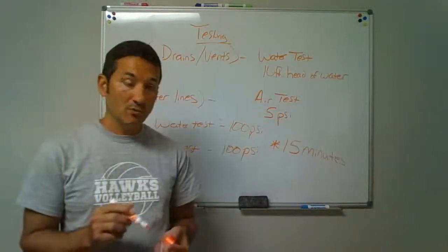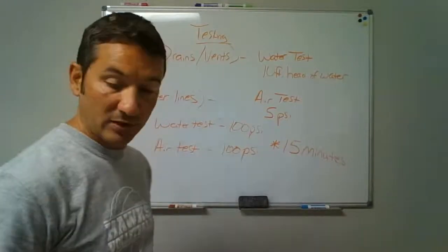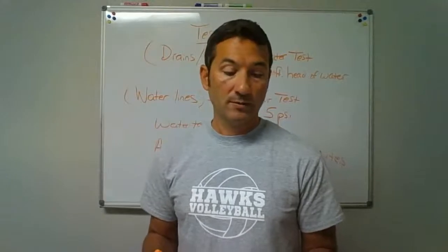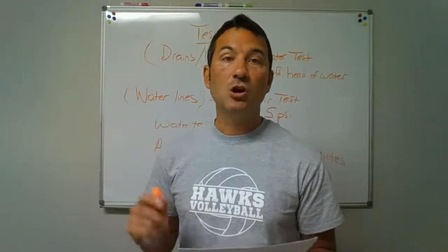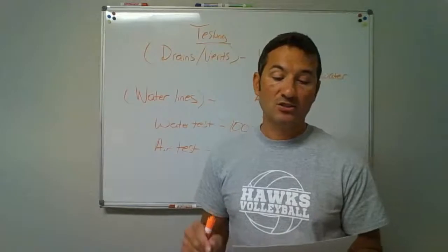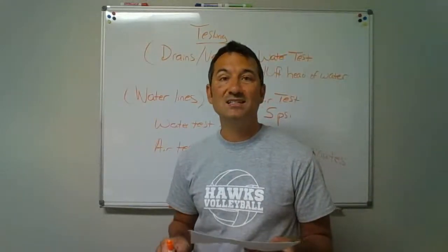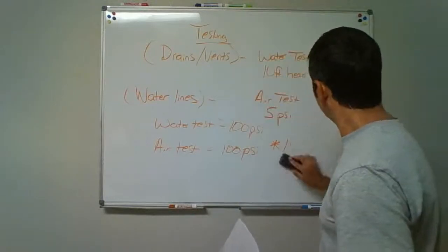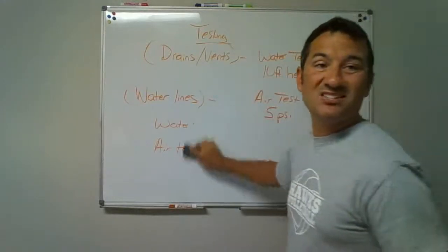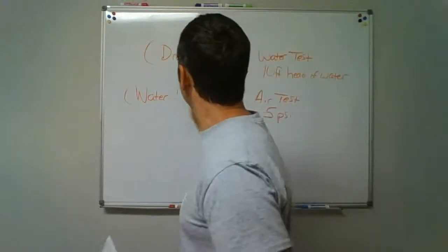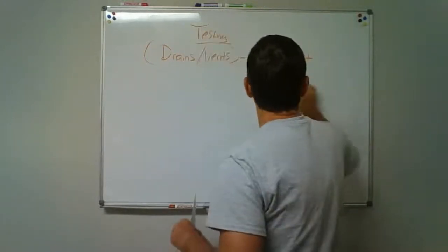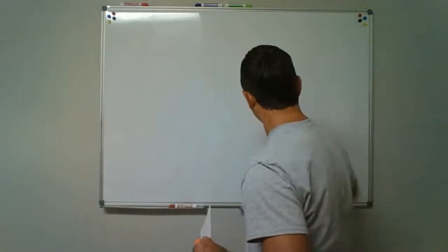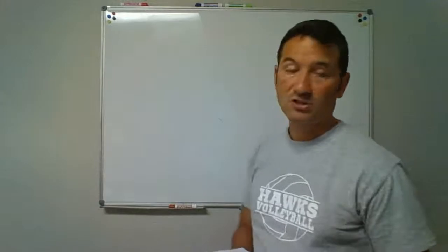Okay. In the 2.5 minutes we've got left, let me cover and review what's going to be on your quiz real quick. Question number 1, when you install the water pipes underground outside the building, how deep in the ground do they need to be? And we drew a picture up there and we said, when installing water lines in the ground, there's 2 parts. You've got to be at least 6 inches below the frost line, being no less than 12 inches. Okay, that was question number 1. 6 inches below frost line, but no less than 12 inches.